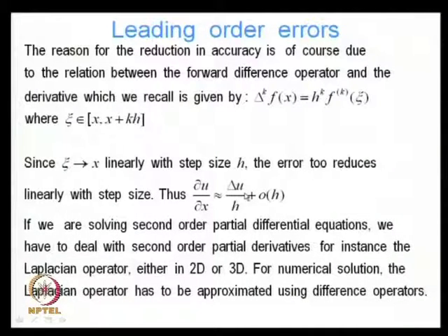That is something very important. Again, we recognize that depending on our choice of the difference operator, we can encounter different error terms. So typically in most numerical algorithms, particularly most commercial codes, they will insist on difference operators or integration algorithms which are at least second order accurate.